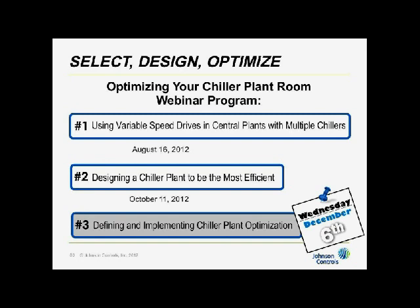When you go up in GPM, you actually lower the head on the chiller because, again, through the condenser, load is equal to flow times delta T. By changing the flow and making it faster, it didn't change the load. All it did was change the delta T across it. And what's entering is still the same number, whatever it is, but the leaving goes down, which reduces the head on the chiller, so you save energy on the chiller, but you may be experiencing greater energy on the pump. So you kind of got to balance those two.